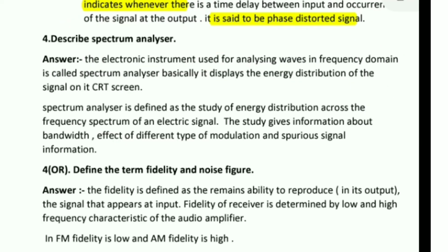The fourth question is, describe a spectrum analyzer. So what is a spectrum analyzer? The instrument used for analyzing waves in the frequency domain is called a frequency spectrum analyzer, because it displays the energy distribution of the signal on its CRT screen.